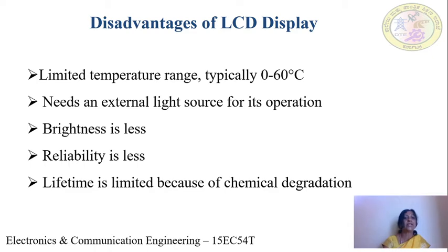So it needs an external light source for its operation. So we are using a backlight here. So in other displays like plasma display and CRT, we are not using this backlight. But here we are using a backlight as CCFL. So it is an external source. That is one extra unit that we require in this LCD. So that may be one of the disadvantages.